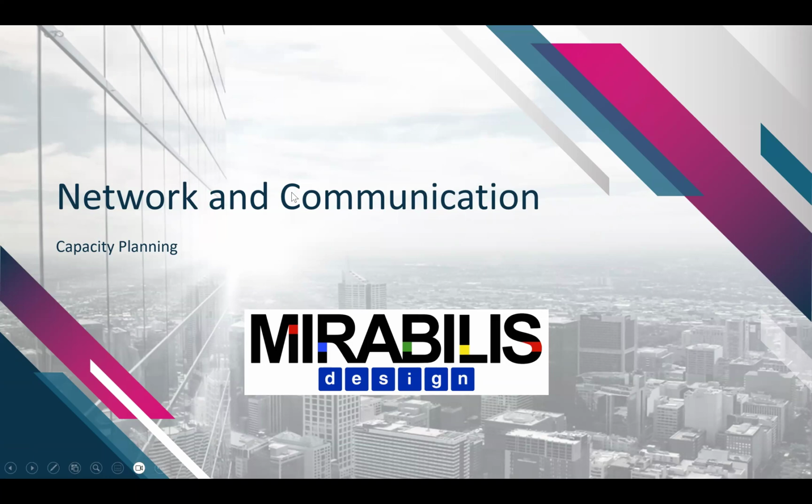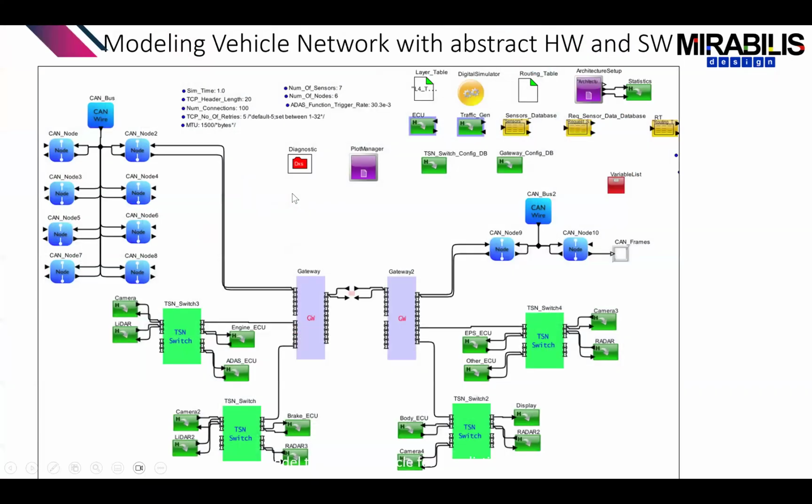So when it comes to networks, the main goal is capacity planning. The capacity planning here is, you create your network by taking in either an ARXML or other kinds of standards that are available. Take those, assemble a model, determine where you want to integrate your sensors, your ECUs, your other subsystems, the connectivity to the data center, all of those. Then, of course, you describe all the other details like the routing table, your bandwidth, your clock speeds, your routing paths, all of those. And once you're done with that, you essentially created your network model.